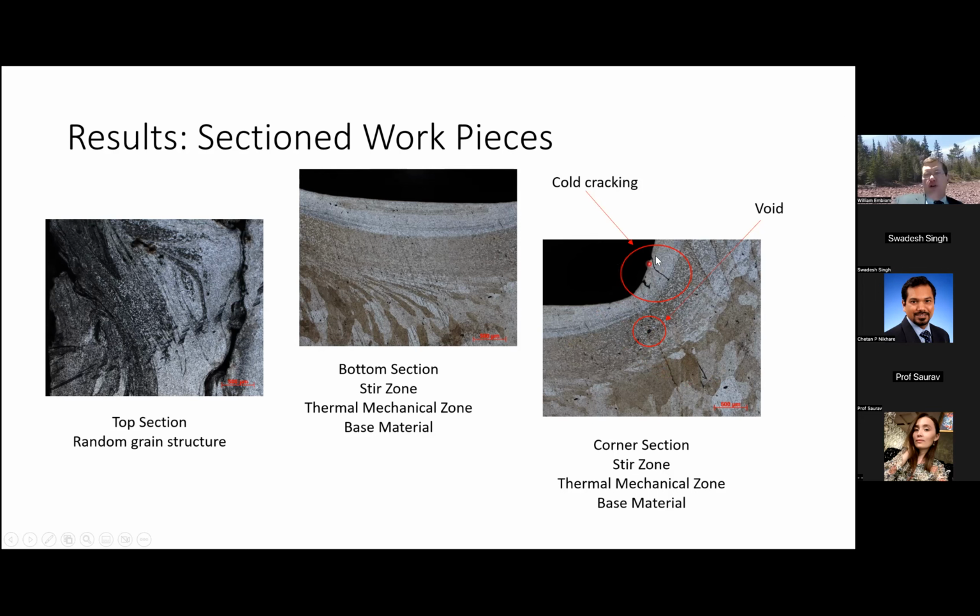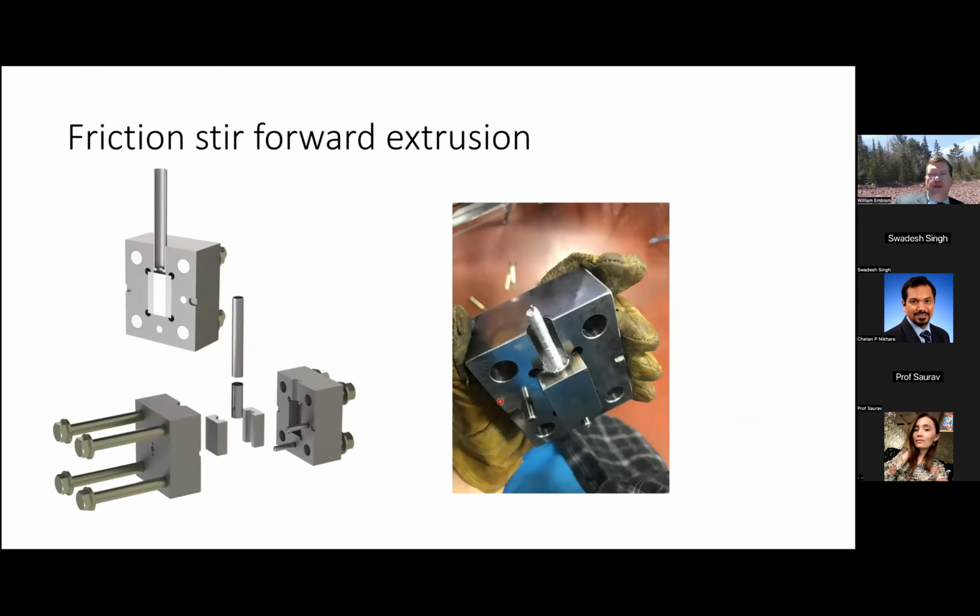So the reason why we have cold cracks is probably because the shop technicians told the students that as soon as you're done and pull the workpiece out of the die, throw it into a bucket of cold water. So a lot of thermal stresses resulting from sudden quenching, and so cracks ensued in the workpiece. However, it's absolutely really cool, and we were delighted with the results. And we're in the process of doing more tests with more improved